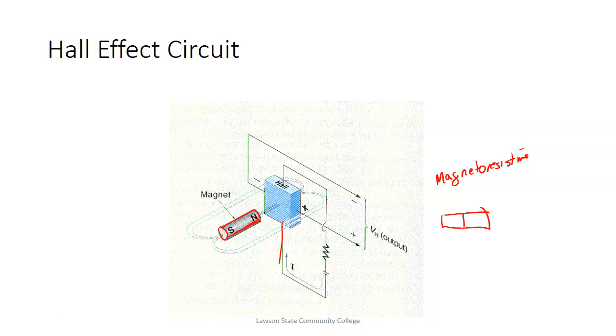I didn't learn about magnetoresistive until I went to a thing with Festo. Festo brought that out to me, and I said it sounds like a Hall effect. It does the same thing, and the guy says no. One of them's a perpendicular field and one of them's a horizontal field, similar to a reed switch. But both of them, I'm sorry, Hall effect and magnetoresistive,